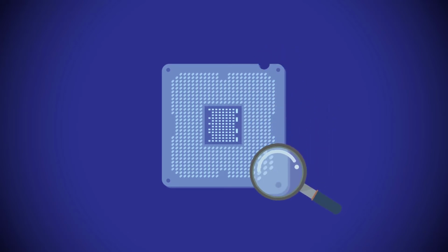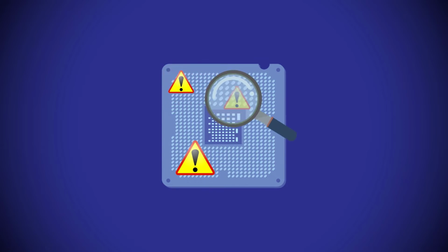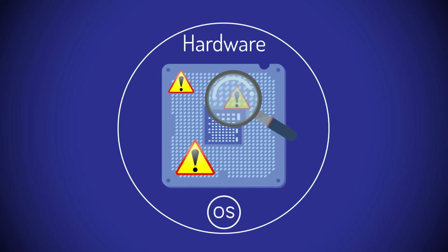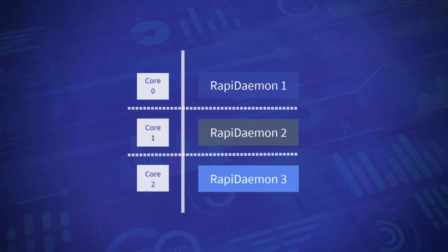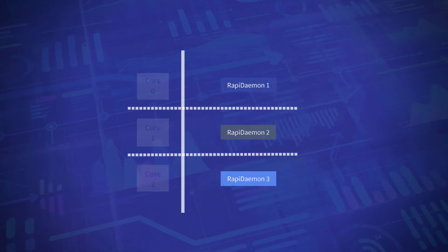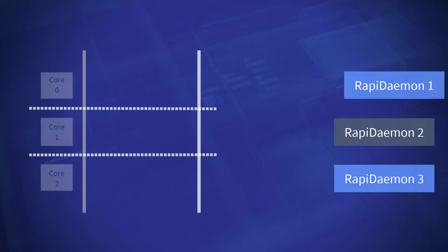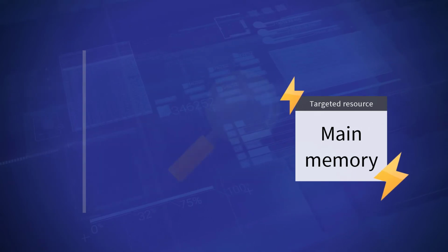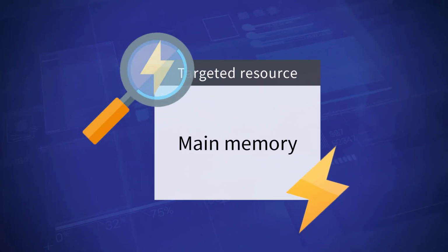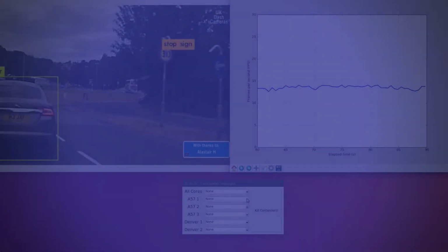The first phase is platform characterization, wherein the platform is defined as both the computational hardware as well as the RTOS. In this phase, we check the outer bounds of possible multi-core interference by competing RAPI-daemons against each other on all cores. RAPI-daemons are applications that create targeted interference on shared resources. Because RAPI-daemons are tuned to stress a single targeted shared resource, this provides a signature of the performance possible when cores compete continuously for that resource. This phase can be done even before application software is available.